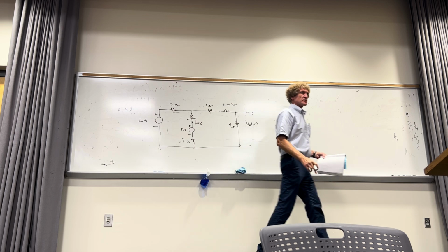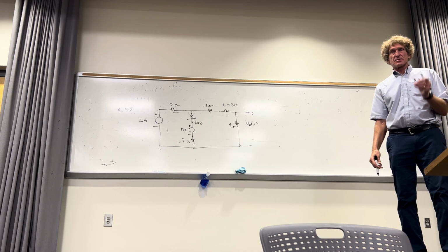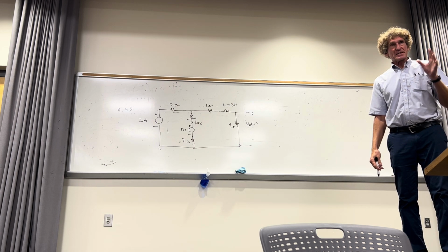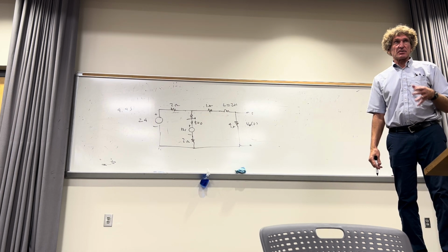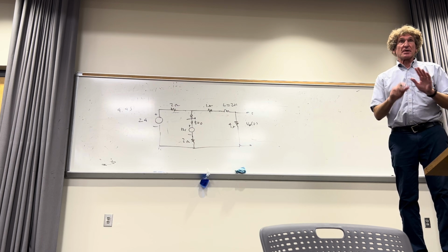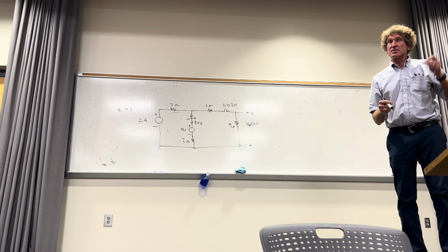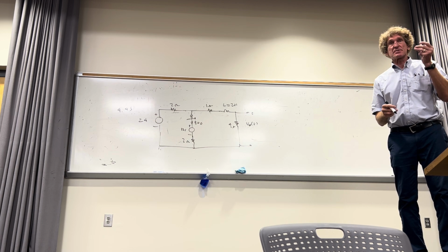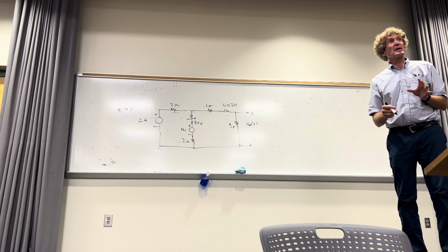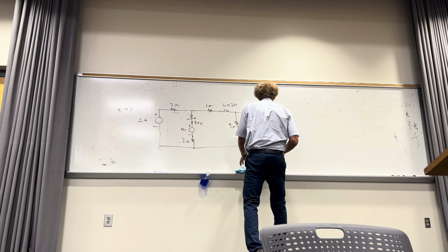Don't worry about the voltage. The only thing you care about when the inductor's in the circuit for these transient problems is the current in the inductor. Y'all hear in class? It's identical in terms of the process and the idea to the voltage in a capacitor. Everything else you want depends on the voltage in the capacitor or the inductor's current. Y'all hear me, class? So first we're going to talk about this.